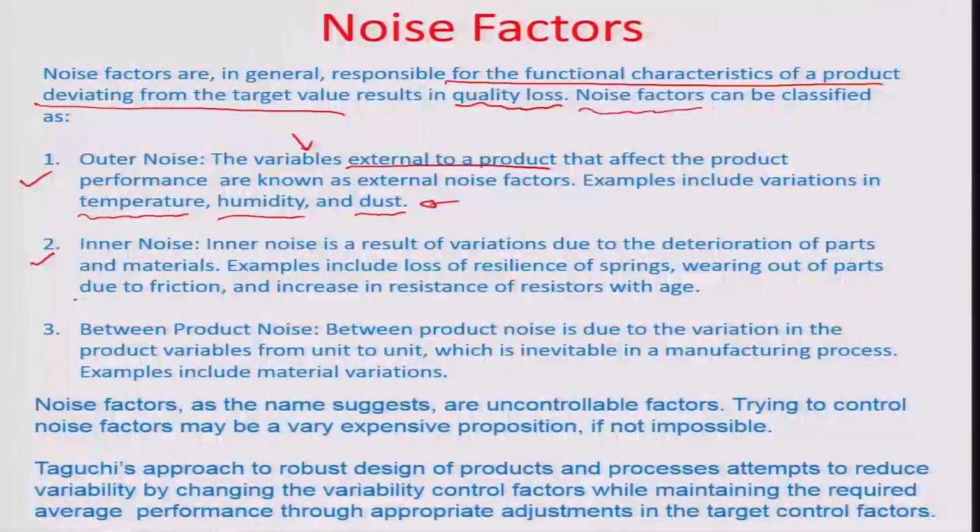Inner noise mostly comes as a result of variations due to deterioration of parts and materials. For example, when we talk about springs, with time there is a loss in resilience of springs, or you can wear out parts due to friction. There may also be an increase in resistance, let's say with age and use, of the resistors in circuitry, and as a function of time such parameters keep on changing and contribute to uncontrollable factors present in the design.